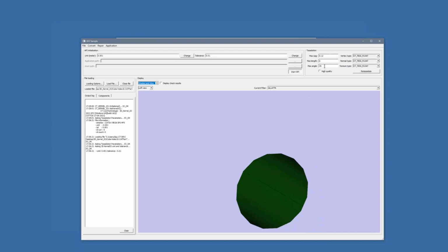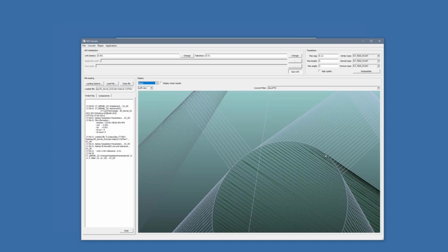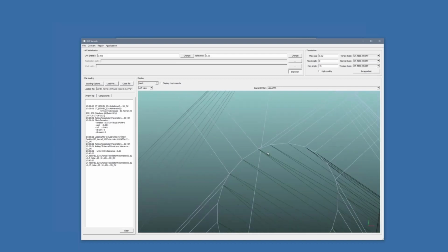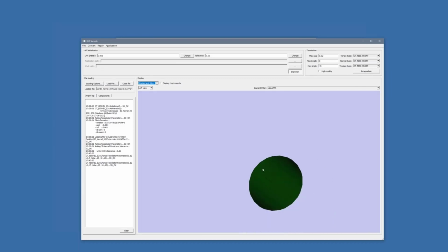Now I can ask our CAD kernel to compute a finer tessellation. For example, there are the criteria on the top right of the sample application, and I will put, for example, 5 degrees and ask to compute new triangles. And now, as you can see, it's far better. If I do a mesh visualization, you will see there are far more triangles. I will just go back and you see there are fewer triangles. But anyway, they are nice.